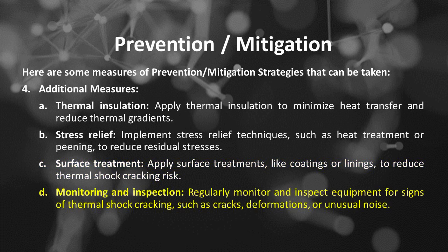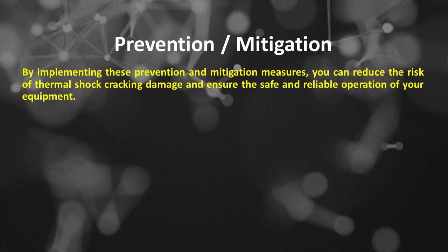The fourth is monitoring and inspection, regularly monitor and inspect equipment for signs of thermal shock cracking, such as cracks, deformations, or unusual noise. By implementing these prevention and mitigation measures, you can reduce the risk of thermal shock cracking damage and ensure the safe and reliable operation of your equipment.